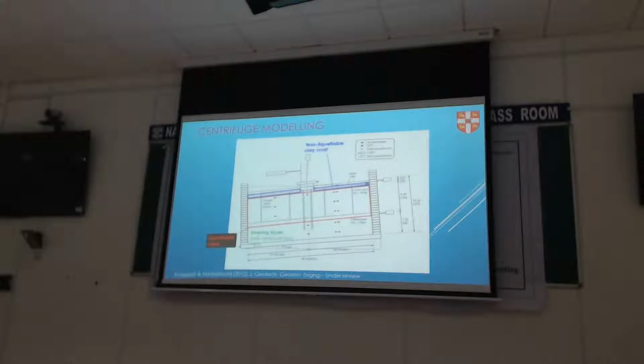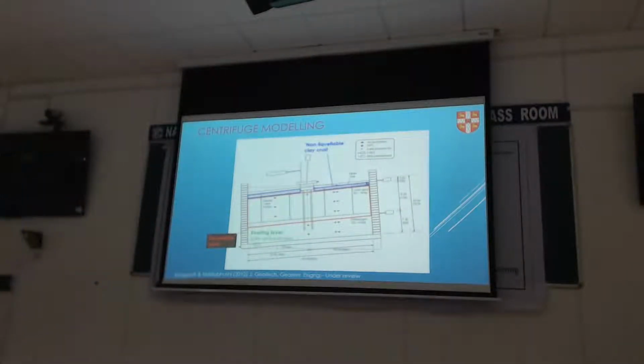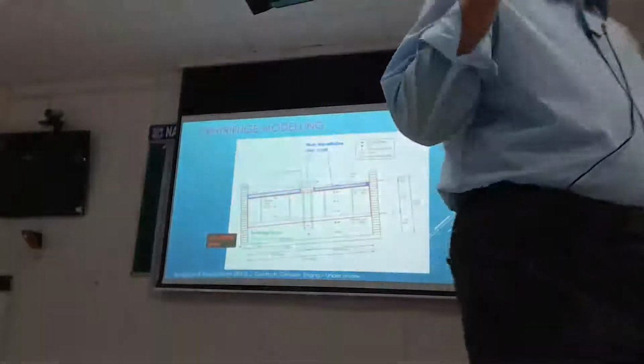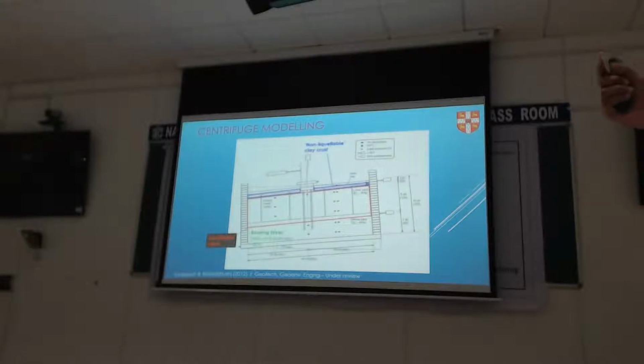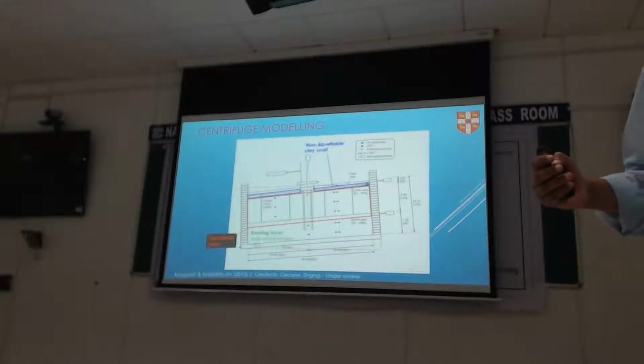Now let's see how all this actually pairs up when we put the data on the. This must be an old slide. It says that our paper is under review. No, it's been published for 10 years now. So about that, I did update the slide. So we did the pile group test, now with the proper axial load, and I'll come to that in a second, and sloping ground and non-liquefiable crust. So everything put together of what we have been talking about all morning.